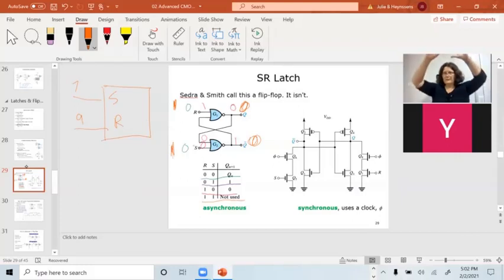I just had these big master counters running my state machines that basically said, okay, I'm going to set the row timing up: on count 1 of the clock I open the row, on count 2 of the clock I do the pre-charge, on count 3 of the clock I'm going to do this, and I have to hold them up for so many states.